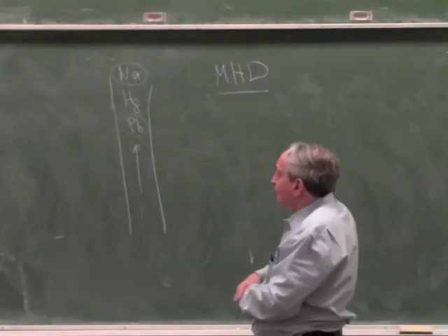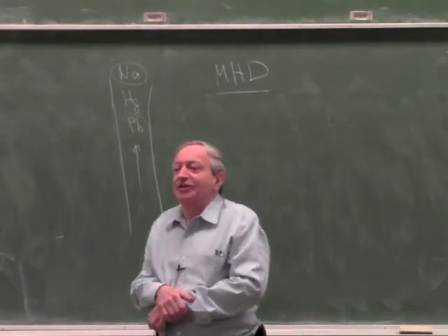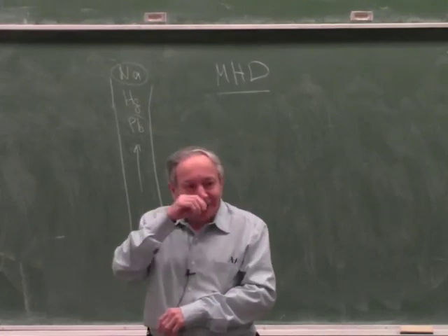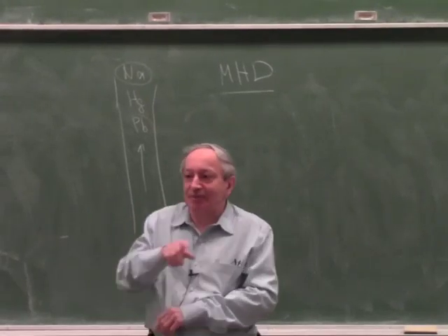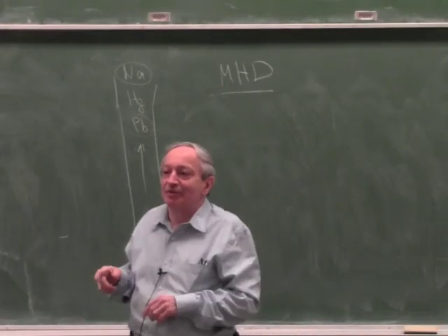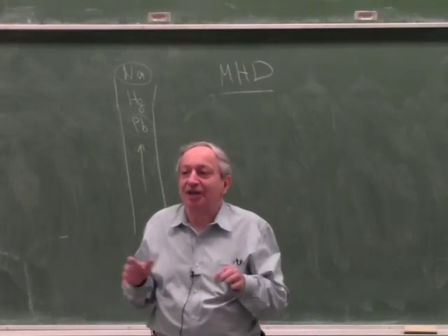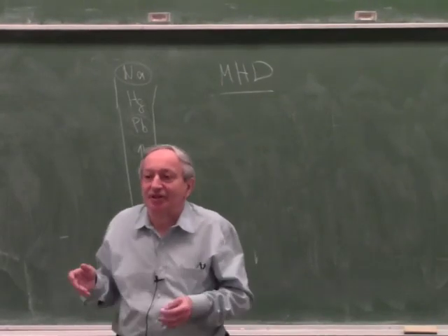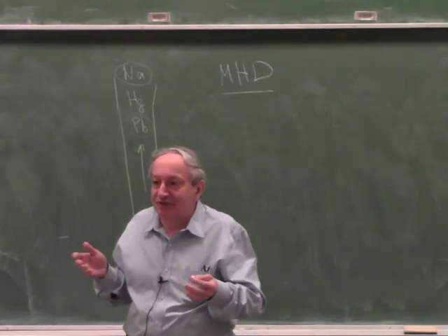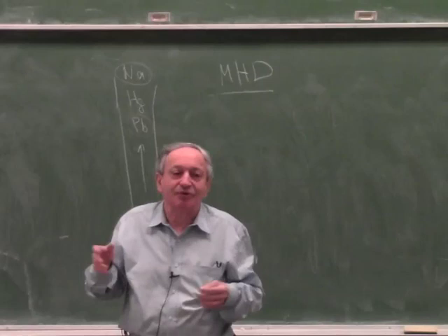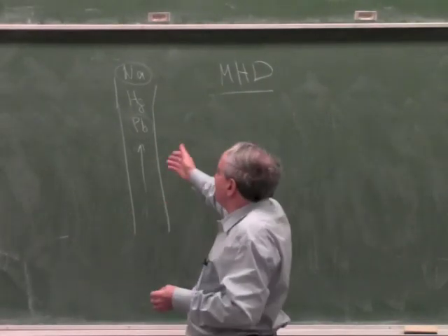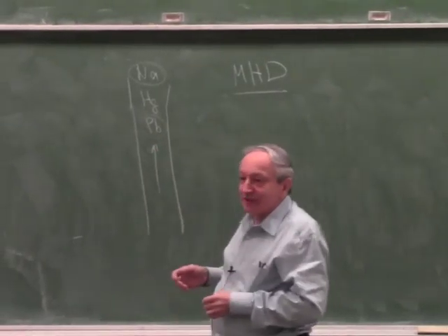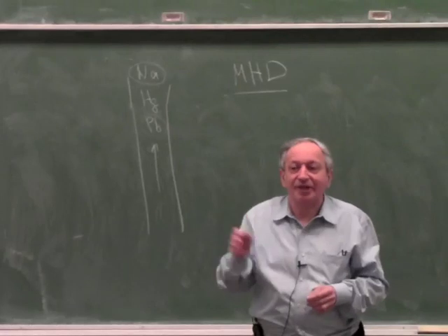And so usually instead of taking and heating up water, which will need very high pressures to keep it at high temperature, a lot of nuclear reactors were designed so that the first heat transfer is done with molten metal, so you can have a high temperature without needing high pressure.